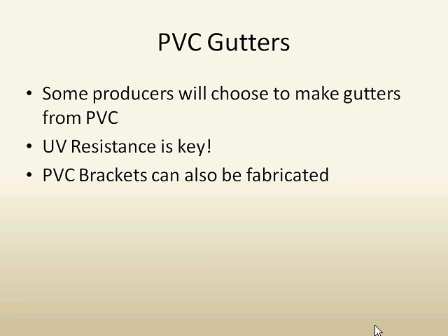Let's talk a little bit about PVC gutters. You will find some producers that choose to make their own gutters from PVC. And a couple things about that. UV resistance is key. You can either buy UV resistant PVC, just have the additive put into it, or as an alternative, you could paint the PVC.